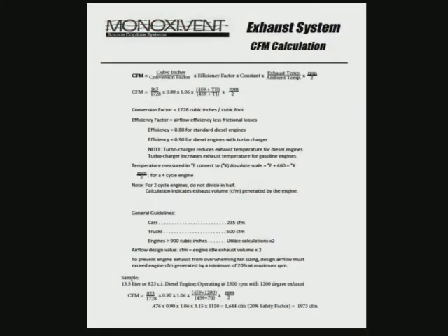Now, if the engine that you're working on does not fit one of these charts that we saw on the previous page, we have a calculation that we can use. We take that cubic inch number, the RPM that they give us, and hopefully an exhaust gas temperature at the test RPM and load, and plug that into this formula, and it will tell us exactly how much that particular engine is pumping out at that condition. So again, cubic inches, RPM, which is the engine speed, and exhaust gas temperature, which is an indicator of load. The higher the temperature, the higher the load the engine is under. We can calculate exactly how much air we need for our system when we're designing it.